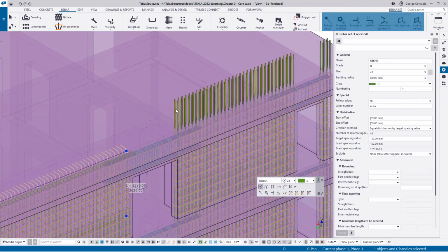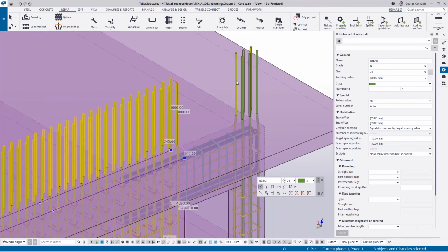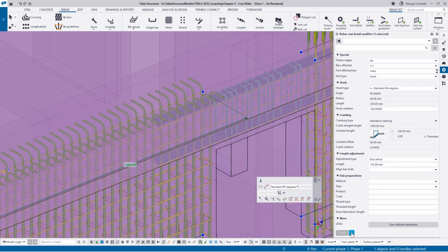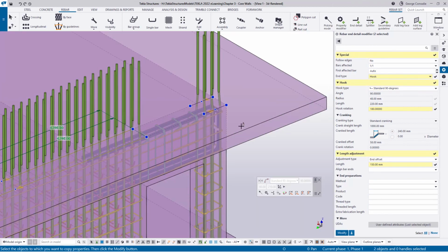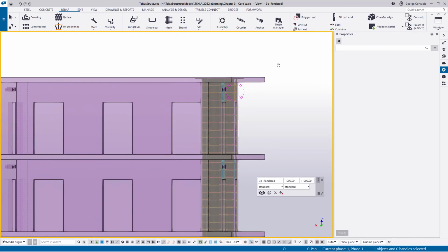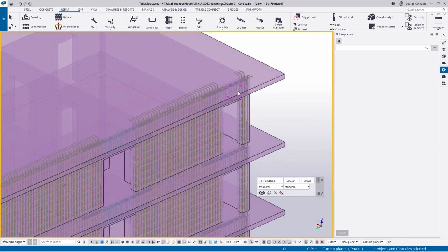So now we can do the same with the others. We can click on this one, this one, this one, this, and this. So we've selected all of them, so their modifiers come up. Then we can click on this modifier and say paint, and then paint this, this, this, and this, holding my shift key while I'm doing that. I say modify, and it changes all of them in one go. And just like that, now we've got our wall ending up inside our roof slab with opposing cogs.